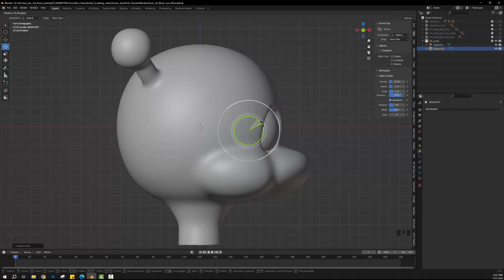Now as I'm doing that, see how we have these little ticks? When you hold the control key, that keeps it rounded up to a number, not a decimal. And if you look up in your upper left hand corner, you'll see it says rotation. Right now mine says 25 on the global, so what I want is 90. So I'm going to do 90.